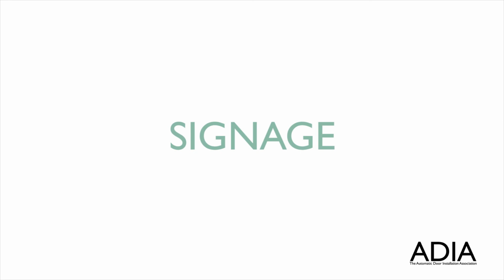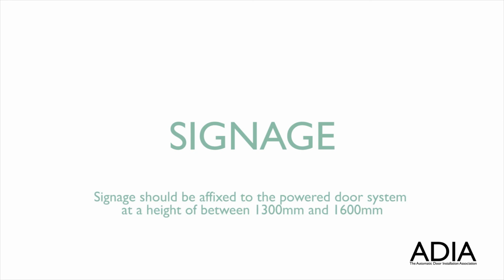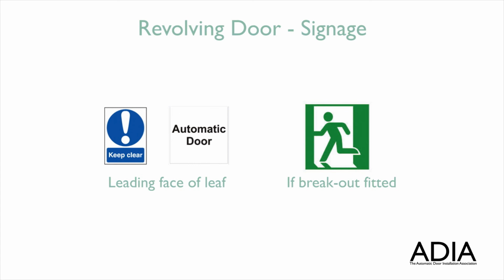Signage. Signage should be affixed to the powered door system at a height of between 1300 mm and 1600 mm. Leading face of leaf, if breakout fitted.